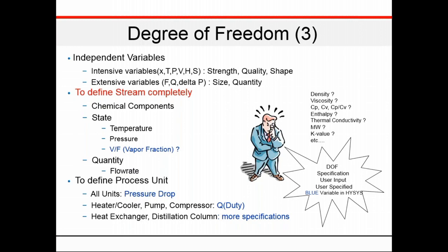So when you have crude oil flowing in, we are trying to define the stream. We first look at what the components of that crude oil are, and in what fractions they appear. Then the hypotheticals: those are the ones with seven carbon atoms and above that we might not be able to describe extensively, but we know they are also there.